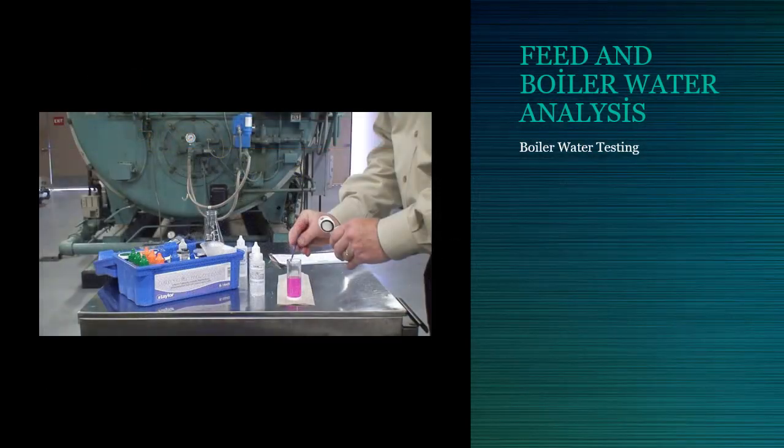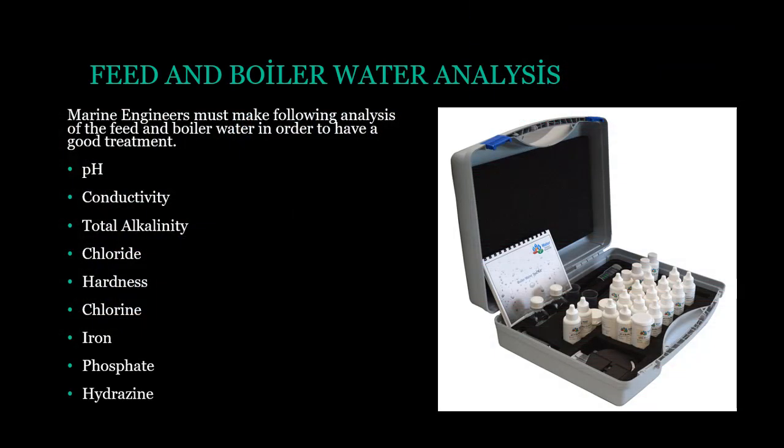Feed and boiler water analysis. Boiler water testing. Marine engineers must make the following analysis of the feed and boiler water in order to have a good treatment: pH, conductivity, total alkalinity, chloride, hardness, chlorine, iron, phosphate, hydrazine.